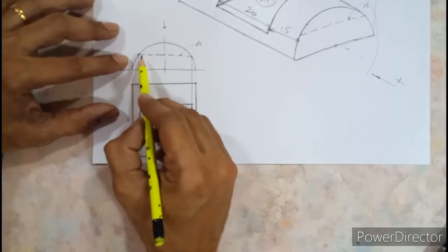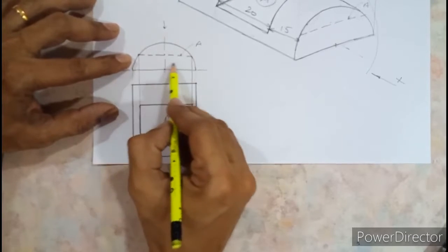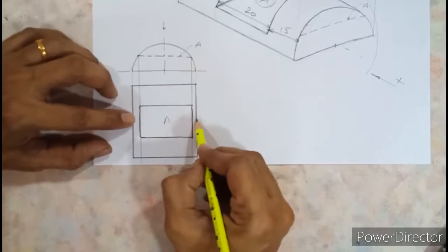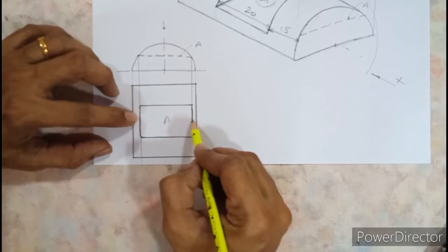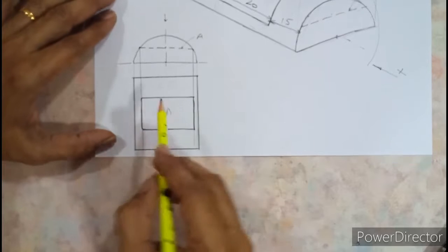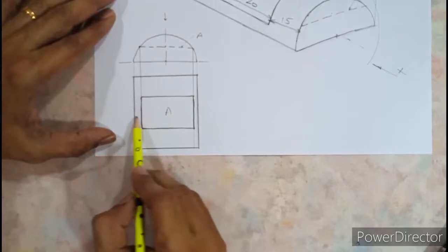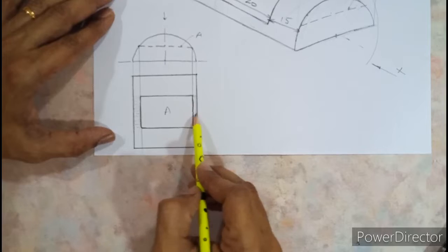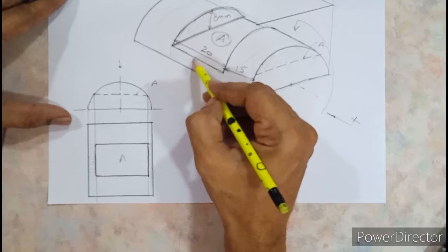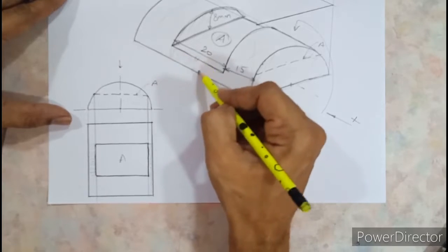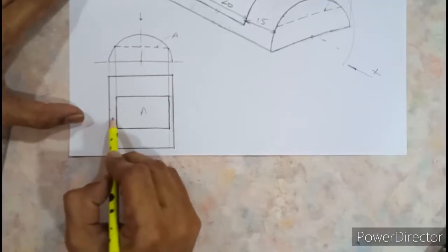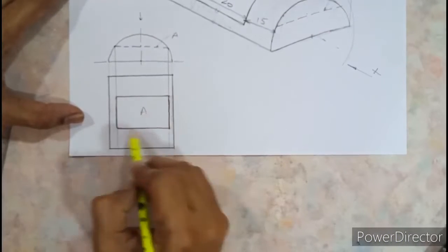Can you understand one more thing: if the hidden line is transferred a bit down, the length of this line will increase. If the length of the line increases, the gap between both the vertical lines decreases, because as you move this down, this will broaden slightly. So the gap between the 2 vertical lines, what I just shaded, this is the first line, this is the second line. This gap resembles a circular surface. It is nothing but a circular surface and not a flat surface. So you need to visualize that this is the circular surface, and in between, this A is the flat surface.